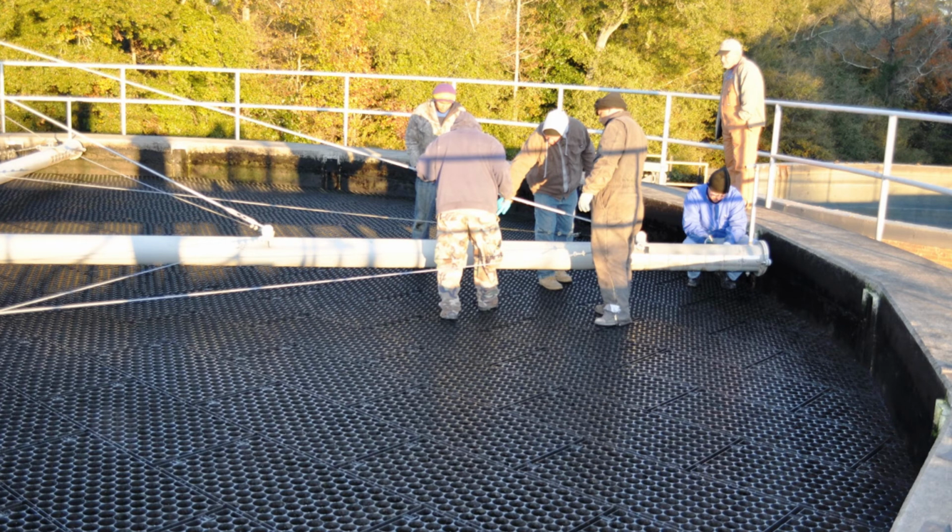Present-day bleaching of kraft pulp uses large amounts of chlorine and chlorine chemicals. Byproducts from using these chemicals are chlorinated organic substances, some of which are toxic, mutagenic, persistent, and bioaccumulating and cause numerous harmful disturbances in biological systems. Enzymes provide a very simple and cost-effective way to reduce the use of chlorine, chlorine compounds, and other bleaching chemicals. Enzymes also offer a simple approach that allows for a higher brightness ceiling to be reached. So far, 2 enzyme-based approaches have been investigated. One uses hemicellulase enzymes, and the other uses ligninolytic enzymes.